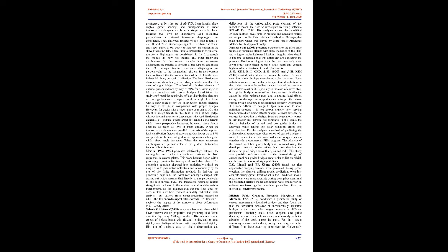This is when the angle of curvature is 30 degrees and a reasonable design for the lateral bracing support system is used. However, with the increase in the spacing between lateral supports, the increase in the deflection becomes much higher.